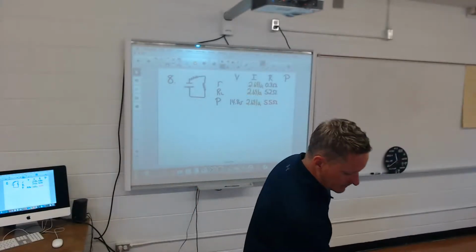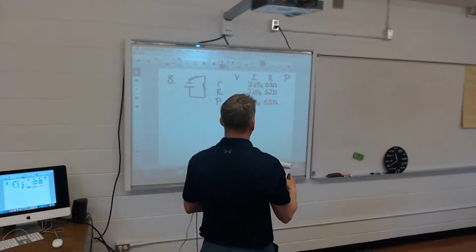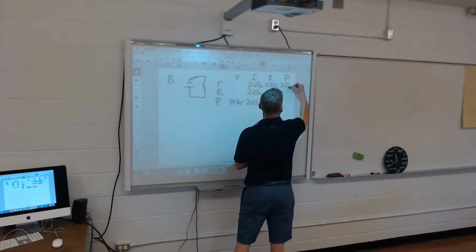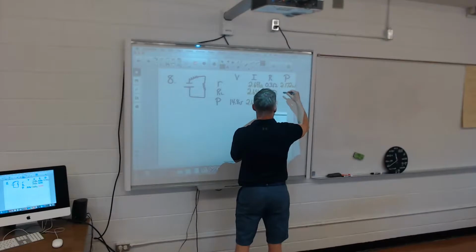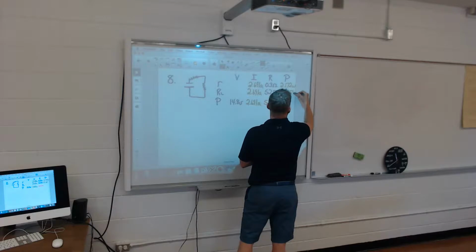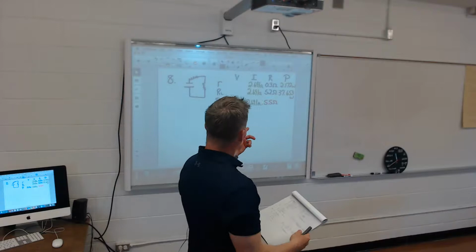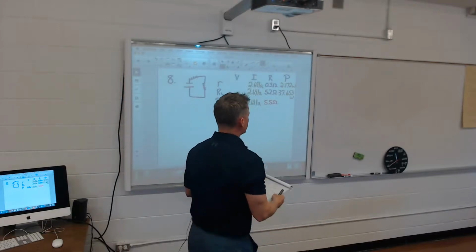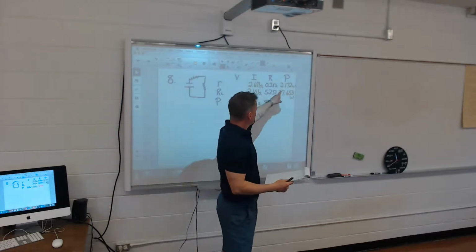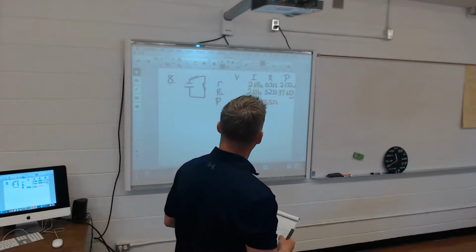So I square the amps and multiply it by the resistance. So on the first one here, I get 2.172 watts. This one I get 37.653 watts. Okay, so in A, the answer is 37.653. In B, the answer is 2.172.